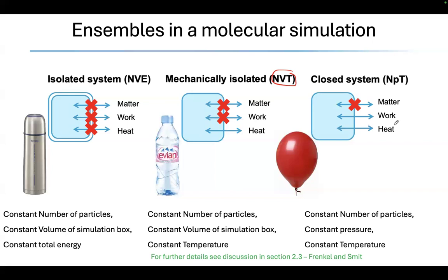So if I say that I want to calculate the density of hydrogen at 5 megapascals and 323.15 Kelvin, since we have chosen to work on this system, then you would choose an NPT system to get the densities, because you know the temperature and you know the pressure at which you want to determine this density.